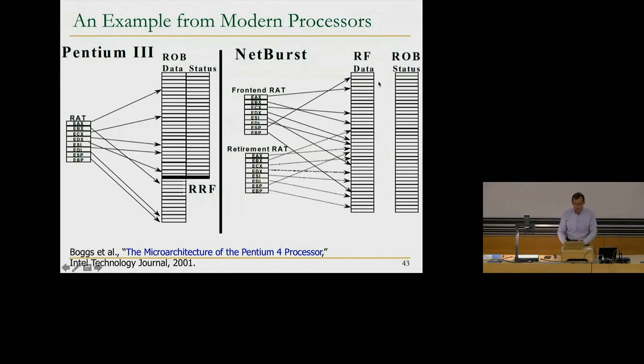And also, this could be very, very big, actually. Of course, limited by the timing issues and the logic that you have. But you can have a 1,000-entry register file over here. It could be very large. You're not bound by anything. Basically, if you need to rename a register many, many times, you need to create new physical registers that it gets renamed to, and having a larger number of registers helps that, so that you don't need to stall the processor.